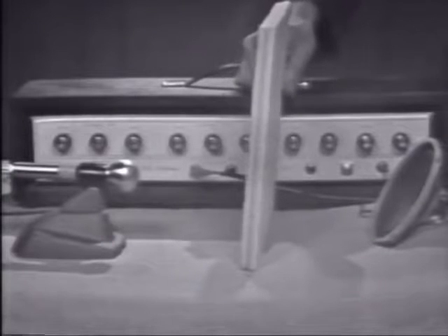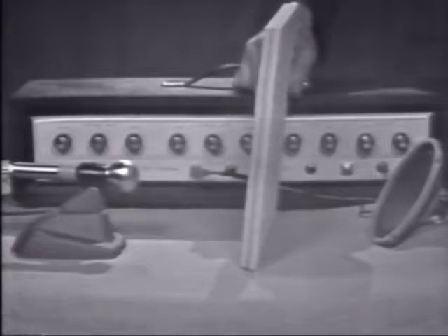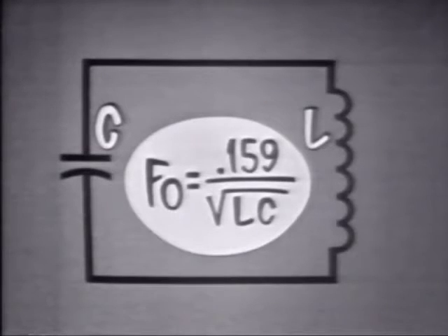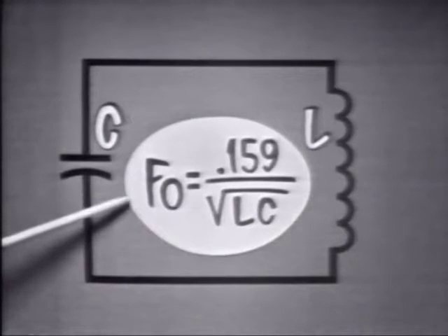We have seen that an amplifier will oscillate without a frequency determining device. But the frequency is determined by distributed LC, which makes frequency difficult to calculate and erratic. This kind of oscillation is usually undesirable. A frequency determining device, in this case the LC tank, provides a stable, easily calculated frequency.